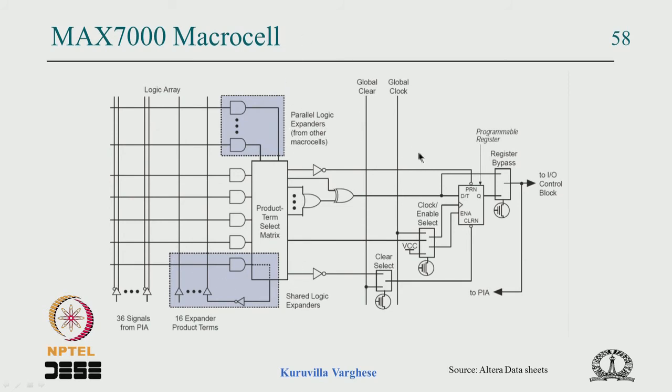Okay, so I think you get a good idea, and this XOR gate can now get its input from one of the AND gates. So the XOR gate can be used for product term optimization. As I said, you can apply De Morgan's theorem, and instead of having Y here, you can implement Y bar, invert it and take the Y there.